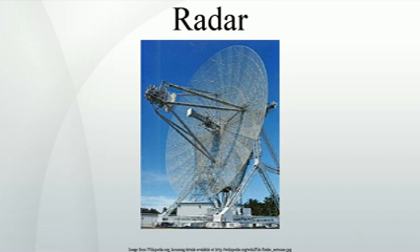Adjusting the timing between when the transmitter sends a pulse and when the receiver stage is enabled will generally reduce the sunburst without affecting the accuracy of the range, since most sunburst is caused by a diffused transmit pulse reflected before it leaves the antenna. Clutter is considered a passive interference source, since it only appears in response to radar signals sent by the radar.